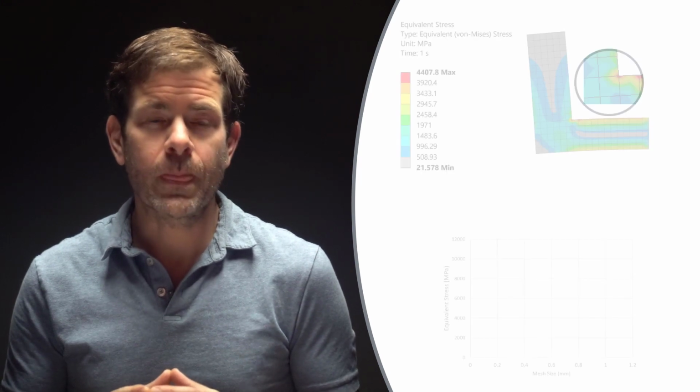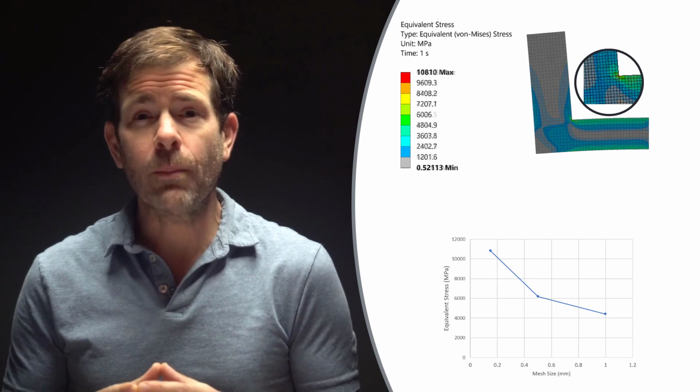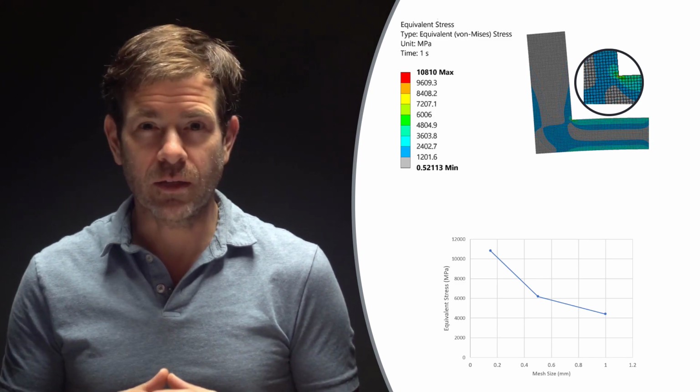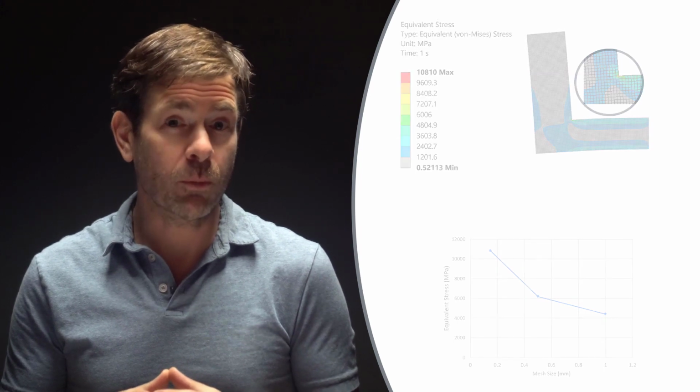To properly use finite element results in stress analysis, one must be able to identify and address situations where artificially high stresses may develop. In many cases, these artificially high stresses will grow without bounds as the mesh is refined. These can lead to confusion as to what is the result that should be reported. Knowing what can be done about the artificially high stress will be a learning outcome from this video.